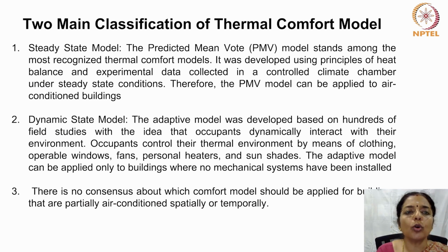So there are two main classification of thermal comfort. First is the steady state model. So the predicted mean vote model stands amongst the most recognized thermal comfort models. It was developed using principles of heat balance and experimental data collected in a controlled climate chamber under steady state conditions. Therefore, PMV model can be applied to air conditioned buildings only.